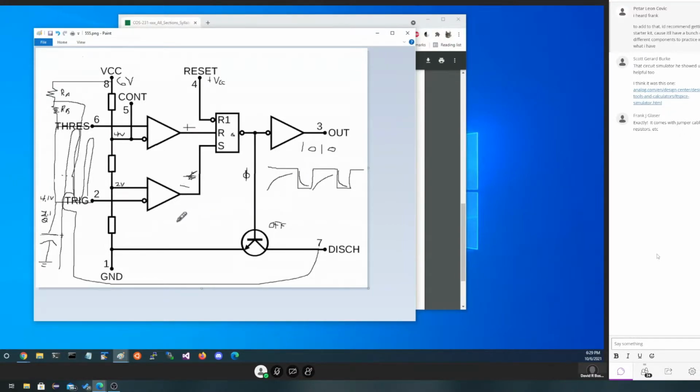Now, when we were talking about periodic signals the other day, we said that the time it takes for that is called a period. And it's going to be measured in seconds. Of course, it could be fractional, like milliseconds or microseconds or something like that, but its unit is seconds. If we invert this time, so it's 1 over the total period, we'll just say P here for period, then we're going to get the frequency.